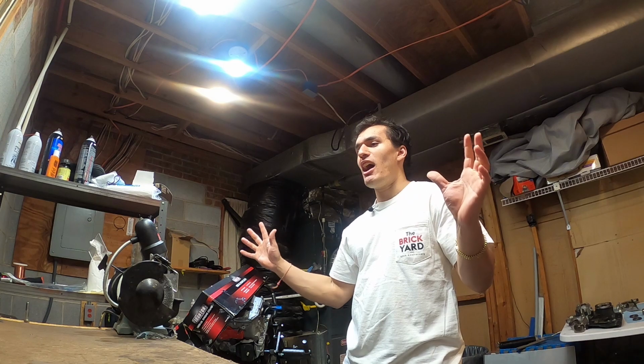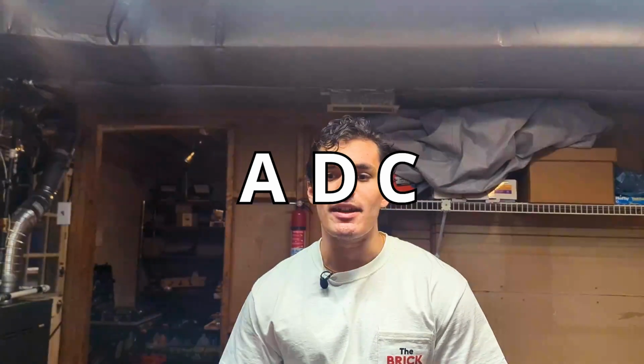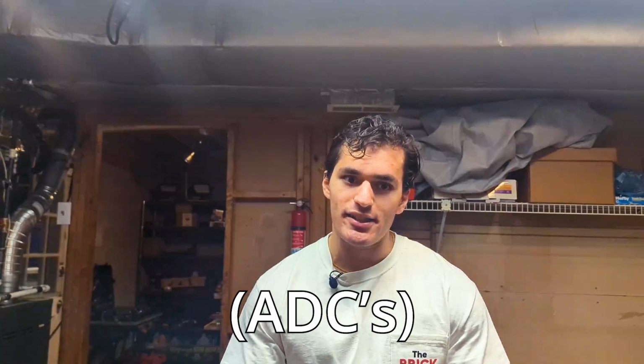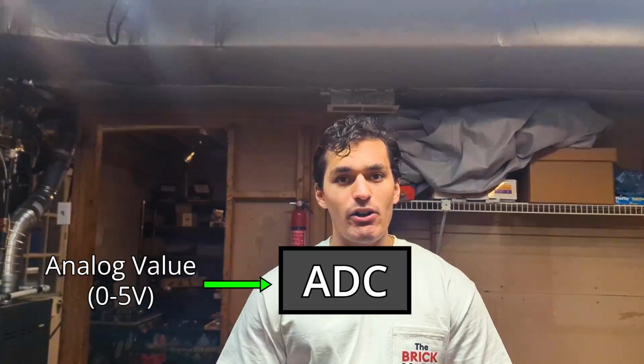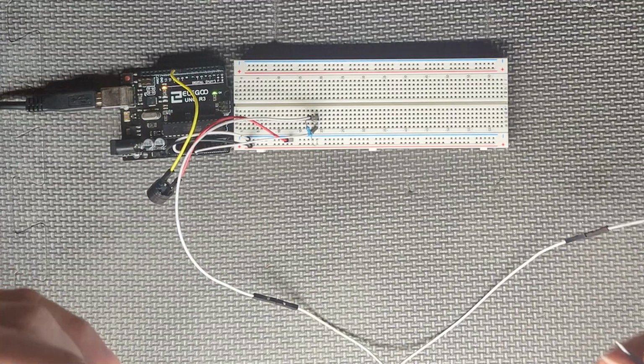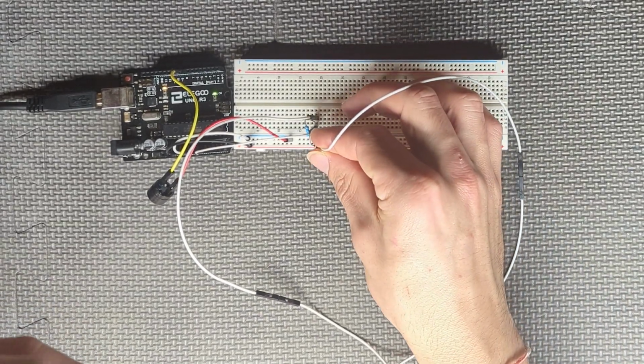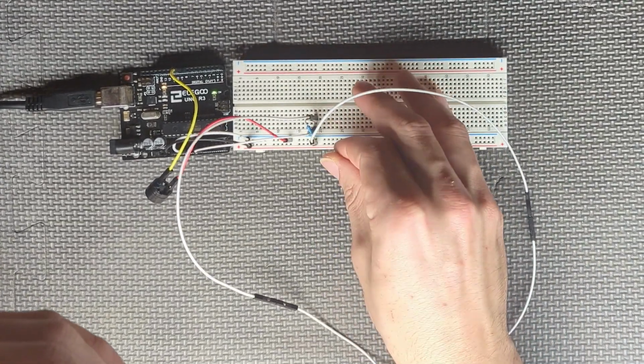The important thing is that now we can read the voltage output from this circuit via the Arduino's ADC. Analog to digital converters, or ADCs, are used to convert an analog value into a digital one. By wiring the A0 pin to the junction of the pull-down resistor and the force-sensing resistor, we can read it as a digital value in our code and do logic based on that value.